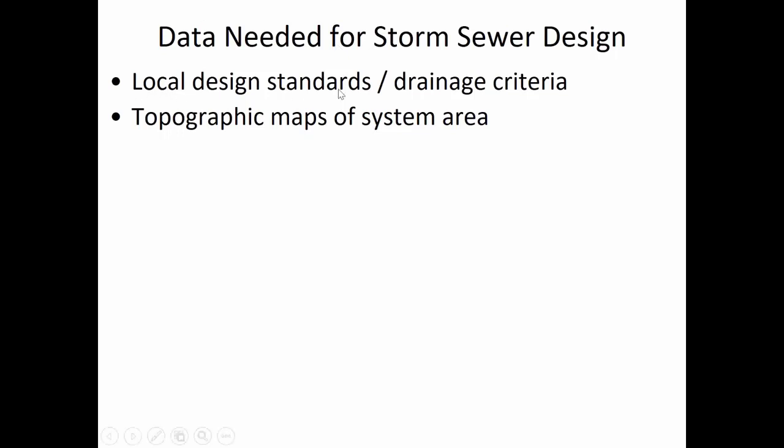So you need to know what the design standards are when you're going to be sizing pipes. And different cities have different requirements. There are some parts of the country and different parts of the world where the standard may be a 25-year standard, meaning that flooding every 25 years is okay. And other places, along interstates, for example, have a 100-year design standard where they don't want water to accumulate by the side of the roadway, and so they design their drainage networks for interstates so that they only fail once every 100 years, or that's the intended design standard.